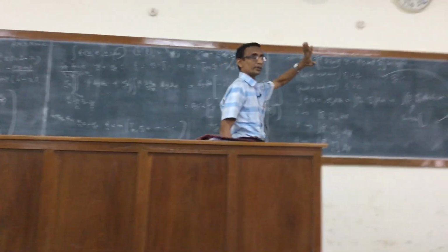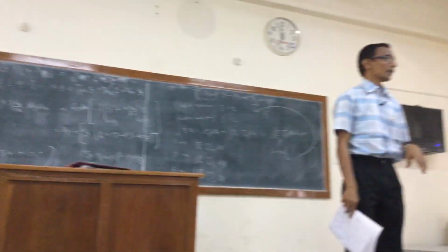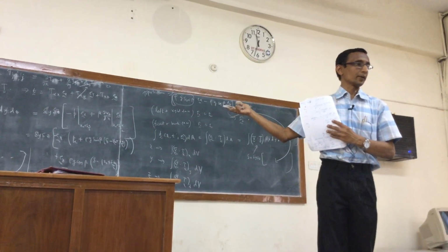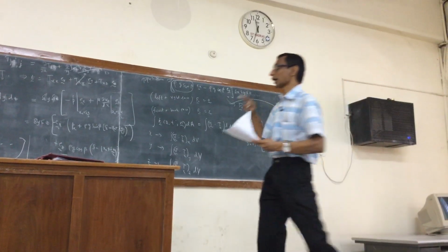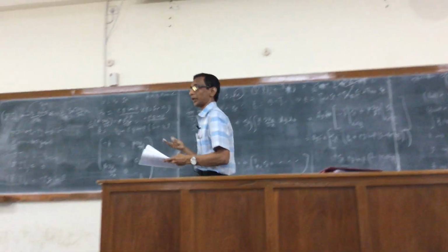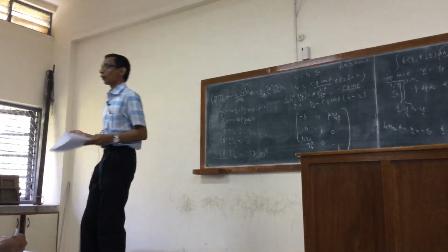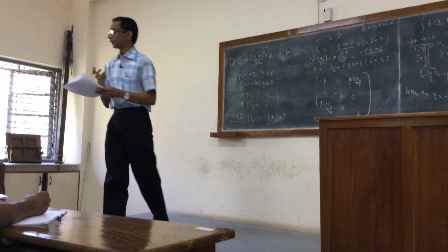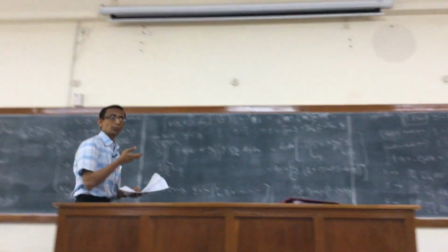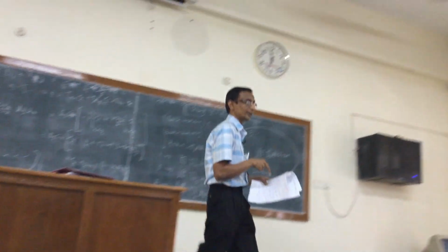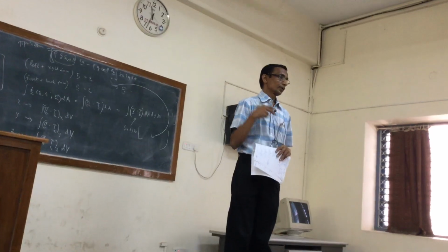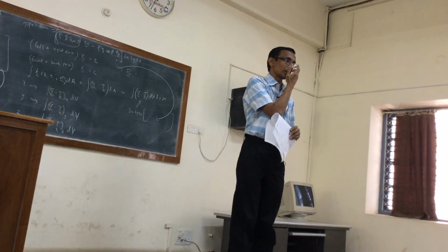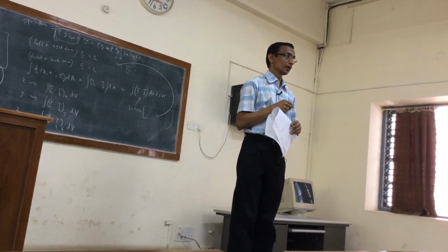If I just want the total force on this, then clearly going through face by face and calculating t dA is not the approach. If I, however, ask you to calculate the force on any one of those planes, then you have to do the individual calculation. But we want it on the volume element, the body of volume that I have taken, right? Then it's clearly easier to do the volume integral. In this case, at least, it's very easy to do. So this also demonstrates the use of the divergence theorem to simplify your force calculation, right?